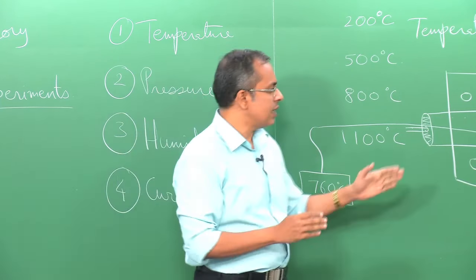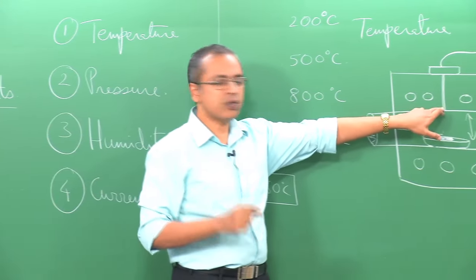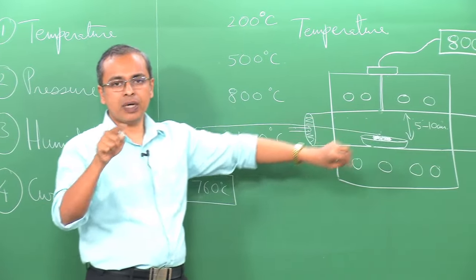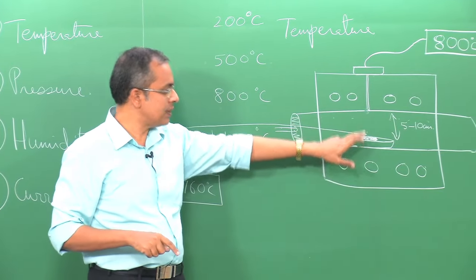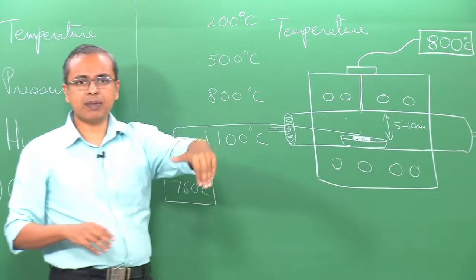And when you understand that, you can figure out if there is a scope for error. So, here we figured out that the location of the thermocouple can therefore give you a wrong idea of what is the temperature, because your sample is sitting somewhere else. So, this idea may not be exactly the same for some other measurement.